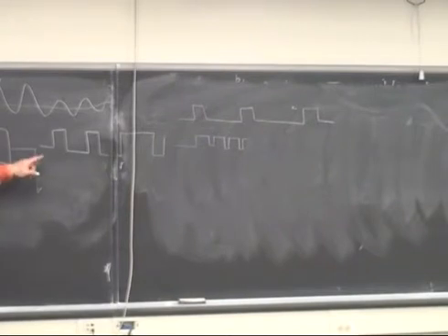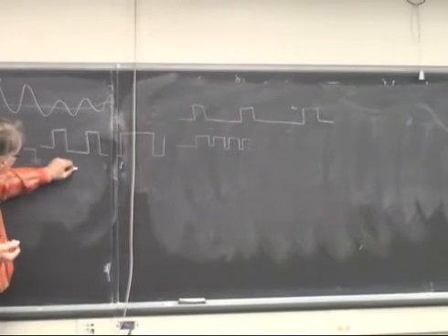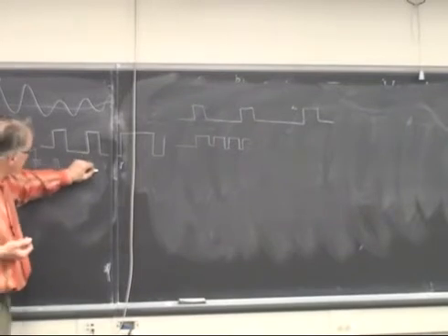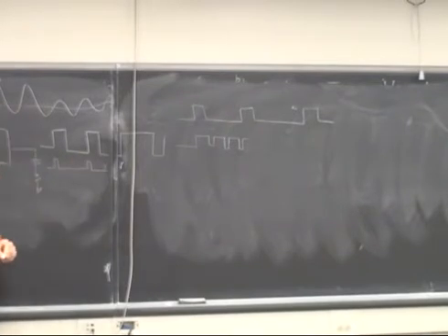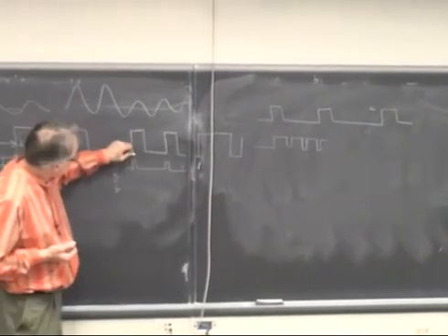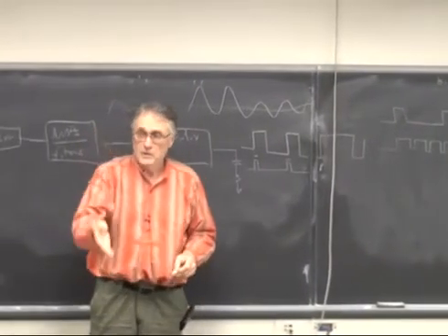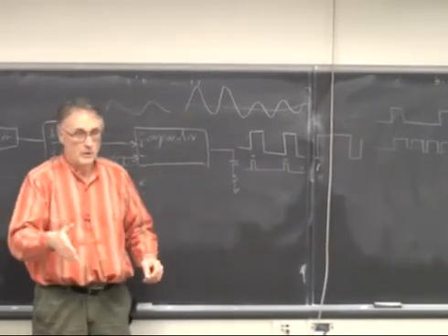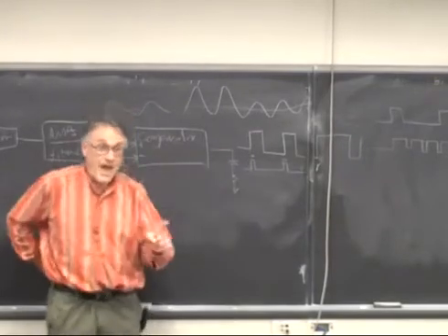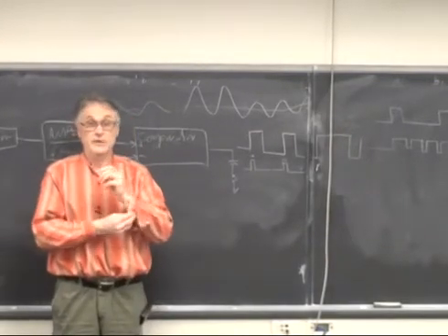All right, so one possibility is to take this output and make it into a pulse train with fixed pulse length independent of duty cycle. So now you take the rising edge here and you make a pulse which is always the same length, one pulse per heart stroke. Then when you integrate that, you will certainly get a rate.